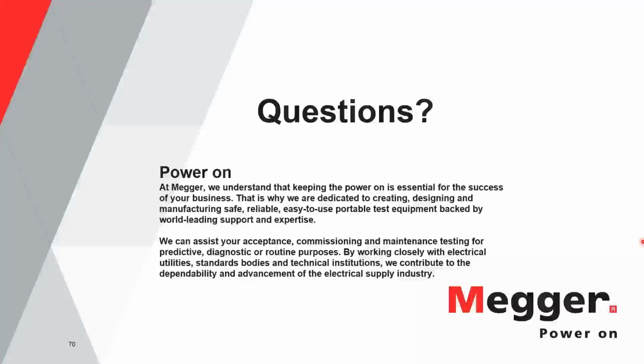Therefore, if we go into the magnitude equation, that would be the logarithm of unity, and that equals 0. So you should see a 0 response all the way up. But when you come off the 0 line and you start seeing distortions and deviations greatly visible on your response, that might be resonance from anything else but your transformer.